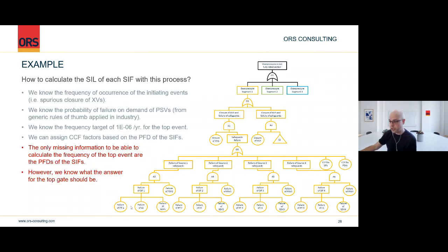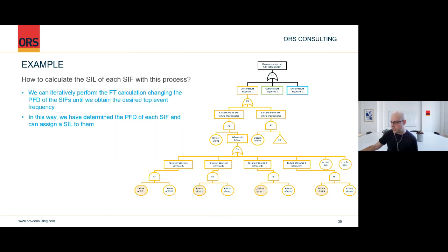You should perform it for each SIF individually, because we have already determined the SIL requirement for each of these SIFs. Now, how you manage them in real life is a different thing. You can just go and test.